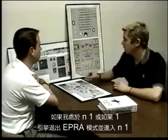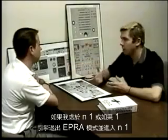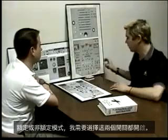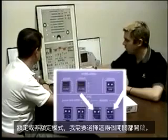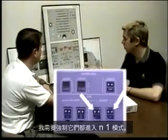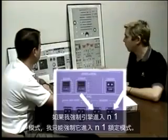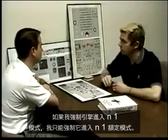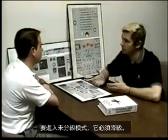If I'm in N1, or if one engine falls out of EPR mode and goes into either N1 rated or unrated mode, I need to select both of these switches to on. I need to force them both into N1 mode. If I'm forcing an engine into N1 mode, I can only force it to an N1 rated mode. To get to an unrated mode, it has to degrade.